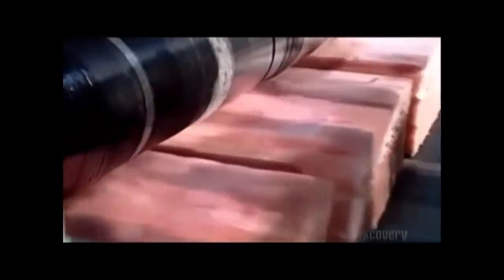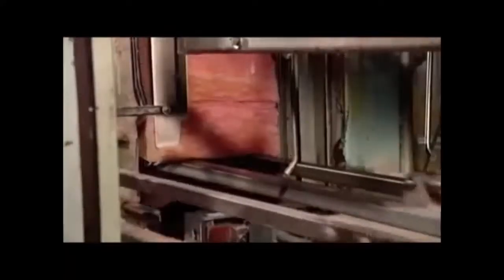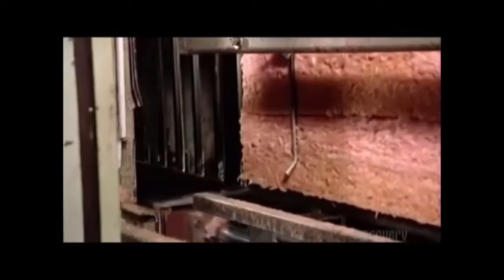After chopping, the conveyor belt accelerates, transporting the fiberglass bats to the next station. A few at a time, the bats plunge down a chute to a mechanical arm which slides the bats into a compression chamber. There, a hydraulic ram squishes the bats down, reducing their bulk 5 to 10 times. This compaction will make them easier to transport.